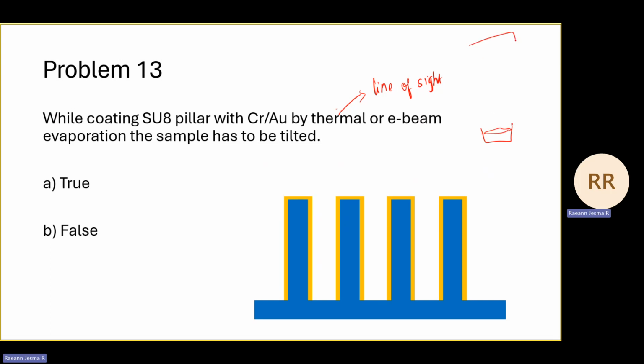We'll have our holder and the substrate which will be clamped to this holder. Then everything will happen in a vacuum based system. We'll melt this material either by using e-beam or thermally by heating the crucible, and this is a physical vapor deposition process.